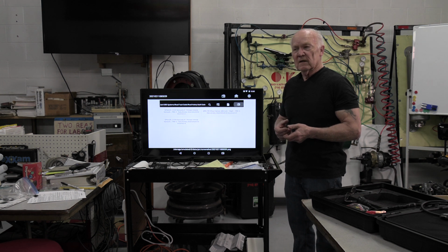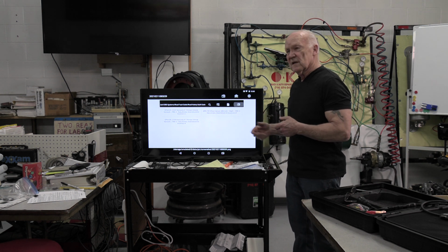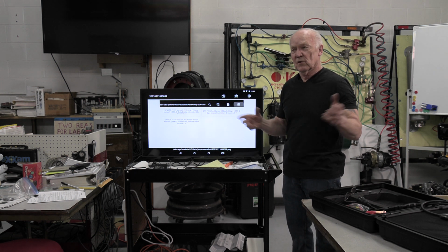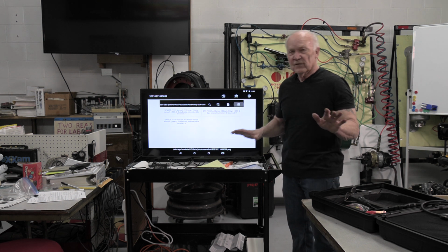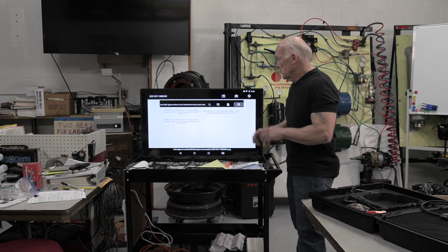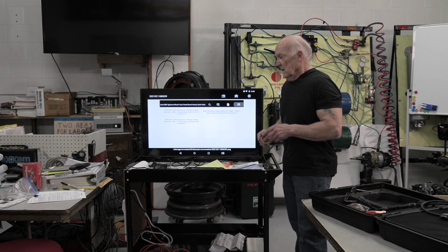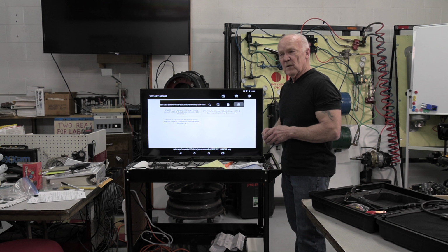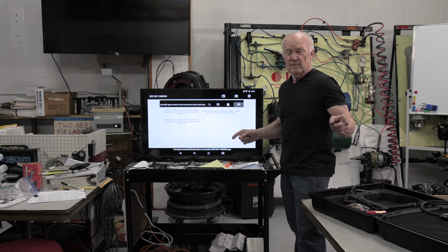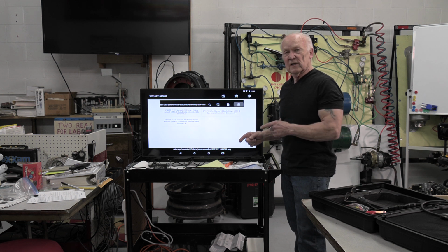Don't try cleaning them. If you suspect a wheel speed sensor, they're usually like $70 or so. It doesn't matter. They're not that expensive. Just change the thing, okay? I try to tell everybody, if you change the wheel speed sensor, get that little extension, okay? Just change it.